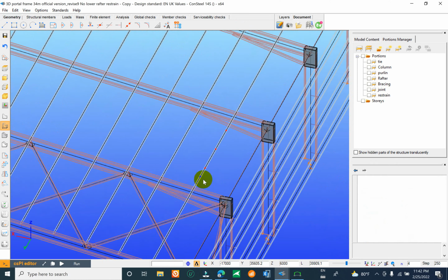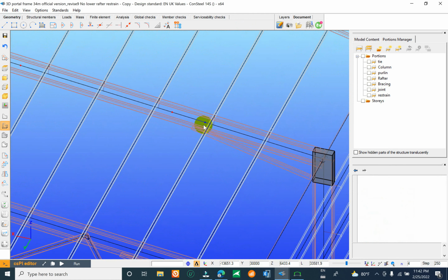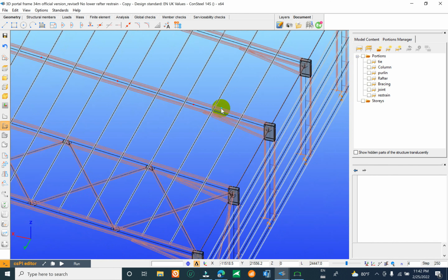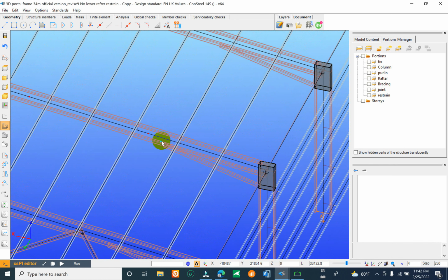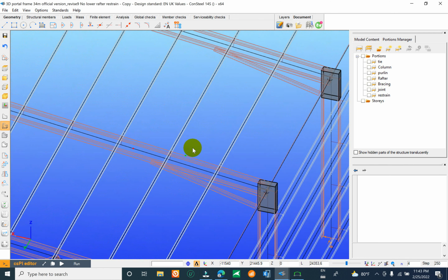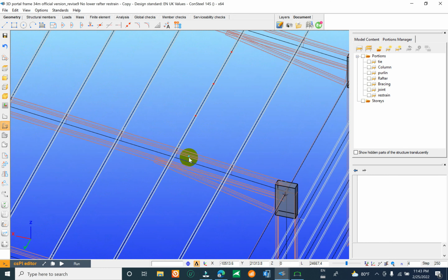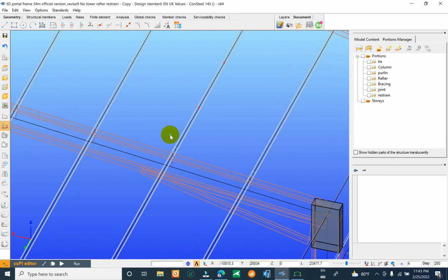Another one is about the bracing from the bottom rafter to the purlin. It is to keep your local section, your local rafter, stable from the applied load, okay, not twisting, not occurring lateral torsional buckling in this section. So the section will get higher resistance to receive the load.